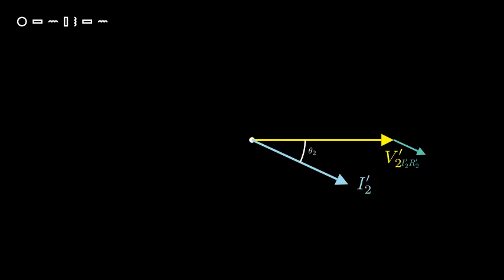The voltage actually generated inside the transformer isn't what the load sees. First, we lose a bit of voltage simply because the copper wire of the secondary winding has resistance. This voltage drop, I'2 times R'2, is always perfectly in phase with the current causing it.